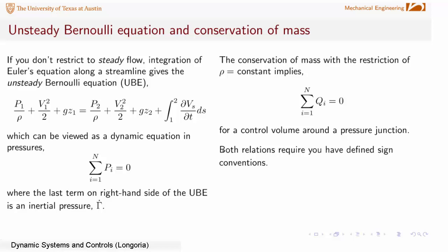I wanted to bring up one other topic that I'd like for you to think about whenever you're modeling fluid systems, and where especially that inertial term comes from, basically the storage of kinetic energy. Typically, what you will study in a fluid mechanics course is by studying and integrating Euler's equation, which is a momentum equation from the Navier-Stokes. You typically will make the assumptions to get to the Bernoulli equation. You recall the assumptions: it's a steady flow, streamlined flow, and inviscid. So there's no losses in there, right?